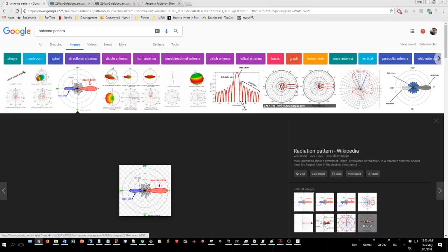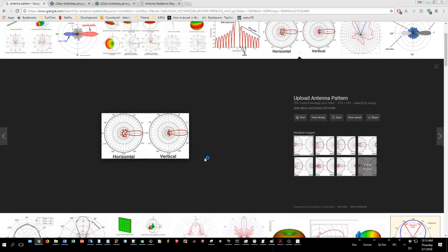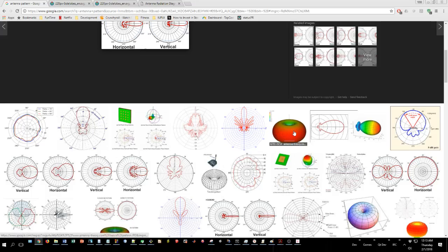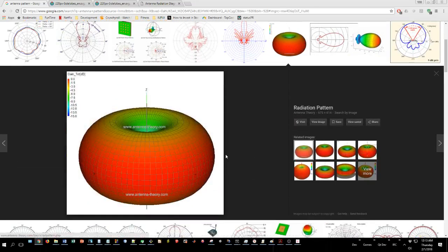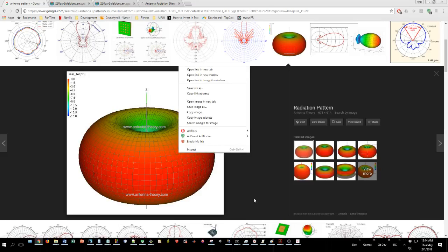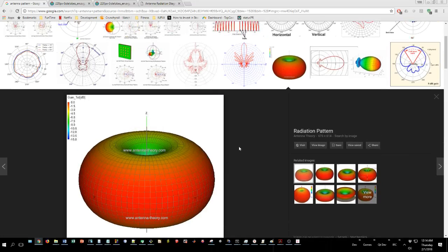So you see that directed antenna. Here's another directed antenna. Now, there's also such a thing as an isotropic antenna. With isotropic, you see all 360 degrees around. It's got basically near unity antenna gain. An ideal isotropic antenna is actually a sphere, but we can't really implement a spherical antenna.